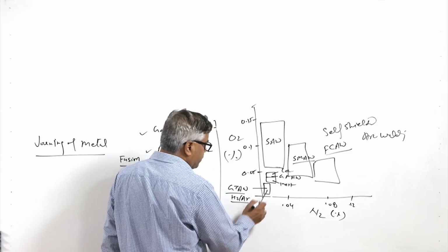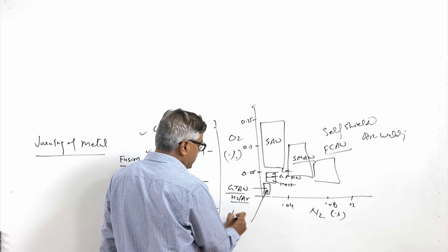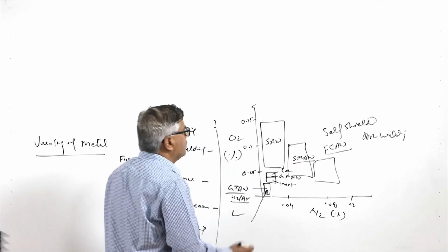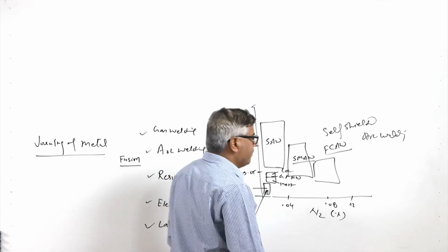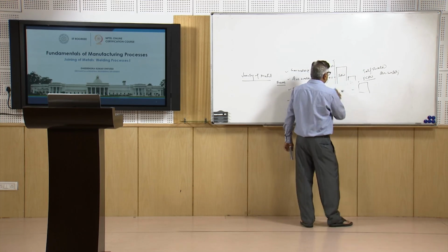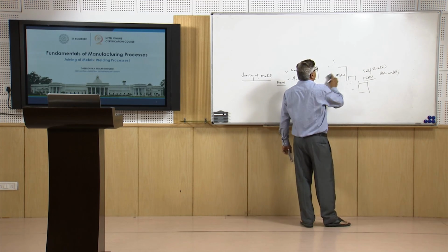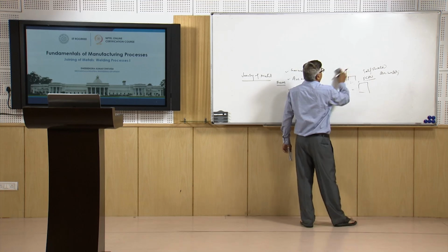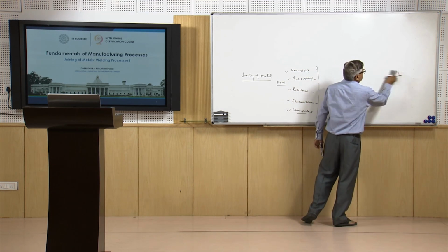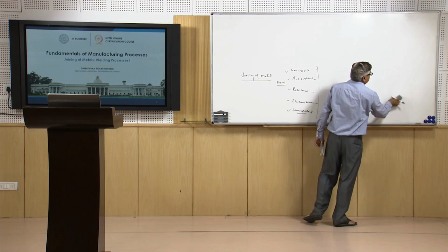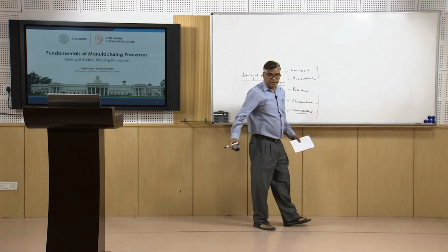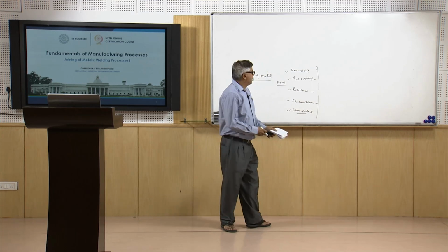The cleanest weld among all these welding processes is produced by GTAW, followed by GMAW, SMAW, SAW and FCAW. The oxygen and nitrogen content in the weld metal reacts with the metal, leading to the formation of oxides and nitrides, and the presence of these oxides and nitrides in the weld metal as inclusions adversely affects the mechanical properties of the weld joint.